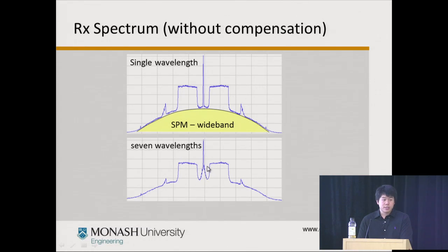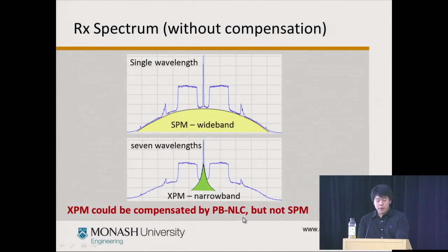So here is what we recognize: we need to somehow clean up this pedestal of noise with a different technique, but we should be able to take out the phase modulation caused by the neighboring channels on the pilot and also the signal fairly well with this method. So we're going to compensate for only the cross-phase modulation and not the self-phase modulation.